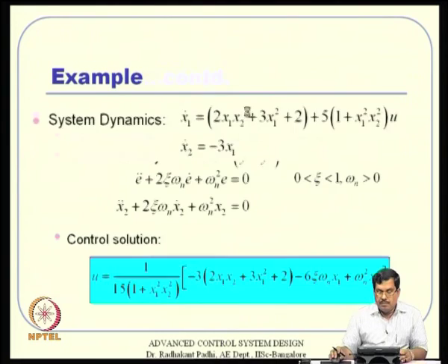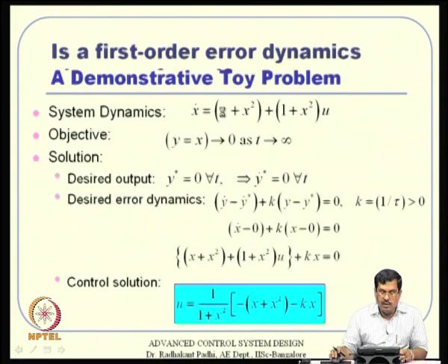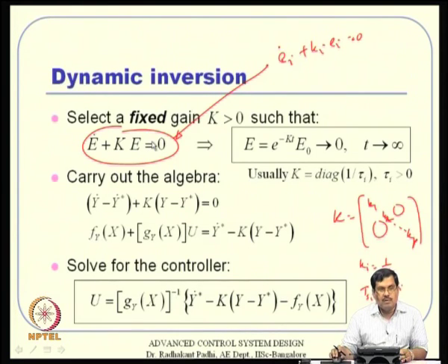Okay. So, in some sense scheduling the gain has a different advantage because of other issues. For example, you want to avoid the slew rate limit or the control derivative limit and all that actually. So, probably you tune the gain a little bit as an automatic function somewhere. So, then it may help you actually. Sometimes people do that, and there also they do not make use of a highly varying gain. It is a slowly varying parameter that you introduce to have additional advantage, but in principle you do not need to do that. You just select a fixed gain k and then you are done actually.